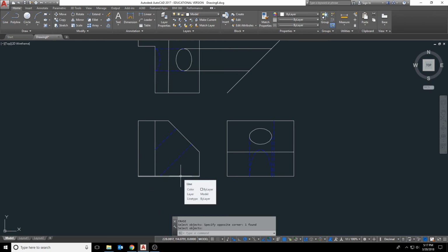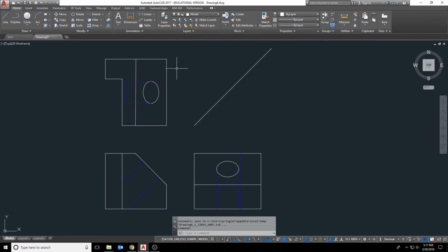So there's a lot of information going on right here just to get a hole that is perpendicular to a specific face. But if we look at this again, here we have our top view with an ellipse representing the hole that's cut through, the hidden lines for that, the hidden lines represented in the front view, and then our right side view. And that is going to complete exercise 5-26.